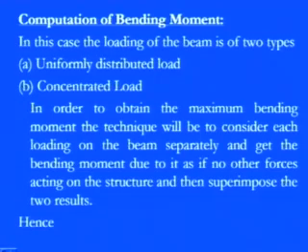We need to go with each separate loading and get the bending moment due to it, as if no other force is acting on the structure, and then superimpose these two results, because first the UDL is there and then the concentrated load. So we need to calculate the different segments and then combine them, because our main focus is that no shearing occurs, only these bending stresses due to the bending moment. That's why we need to compute the bending moment or bending stresses very carefully along with this particular kind of load.